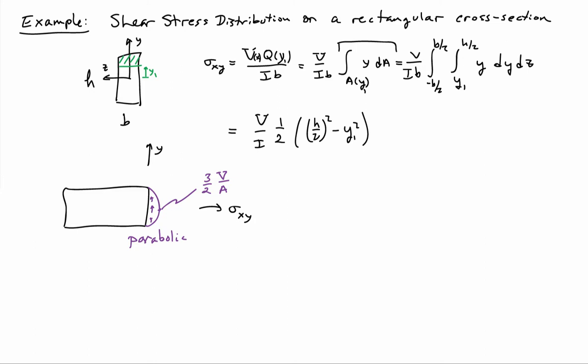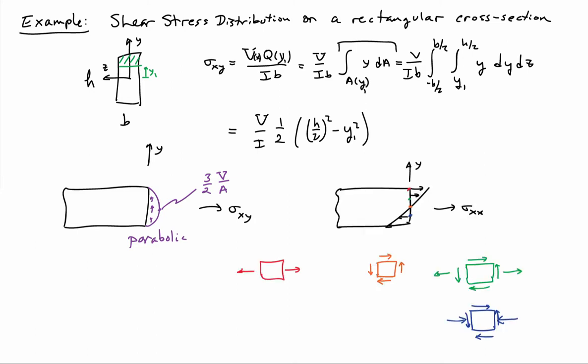That's one of the important reasons for doing this more careful calculation of what the shear forces in beams are. We can also look at what the stress state looks like overall. If I draw in the stress state due to the bending stresses on the cross-section, I have a linear variation, and we can plot at different locations. At the red point, at the top of the beam, I only have bending stresses, so they're just normal stresses in the x direction.